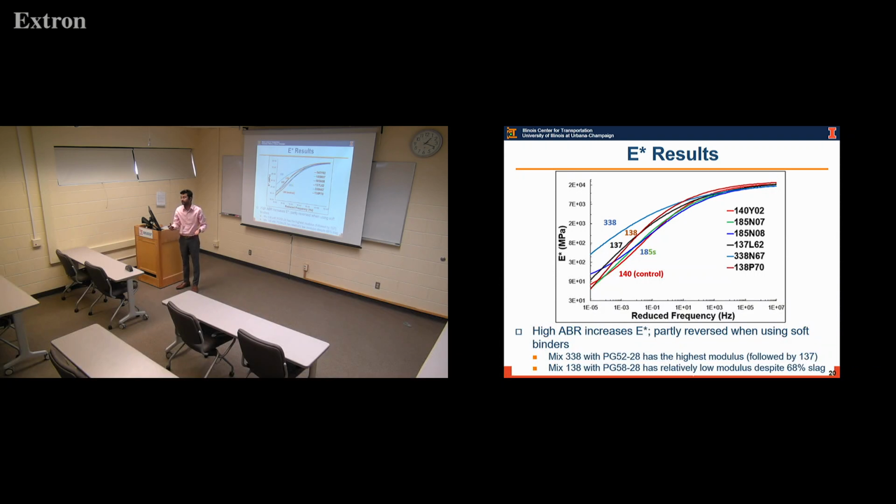So we try to assume that when we are compacting, let's say in an area of 2 meter or 3 meter range, the mixes will be pretty much the same, compared to if I go 100 meters off that particular location for the second layer and collect the cores. So it's very important that you collect the cores from the previously collected site, very close to it, so that you can avoid that kind of differences. There can be other ways to ensure that, by image analysis, where you can see that the structure is similar to what you had before, and then you can take a call whether you need to consider this as a valid sample or not.